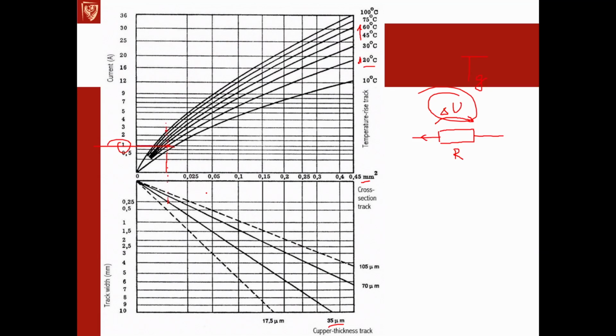So you should have lower current, which also means that it's always better to use as wide a track as possible, at least for low frequency boards, because for high frequency this results in higher capacitance and inductance, which we don't really want. But that's another issue. For the majority of PCBs, it's always better to use wider tracks, like here with 0.75 millimeters, which is 24 mils, because with this track you still stay within 10 degrees even with more than 1 amp flowing.